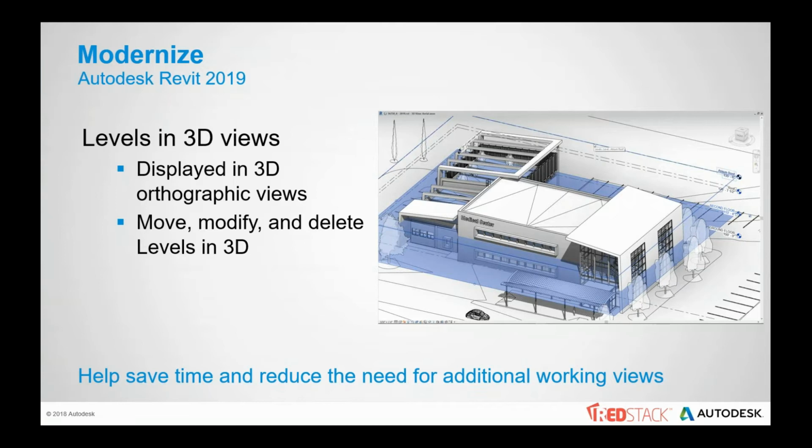What it does is it gains better insights into the important datum heights in your project with 3D display of level elements. So the new file displays levels in 3D orthographic views, while upgraded files have levels in 3D views turned off. This all helps you save time and reduces the need for additional working views.